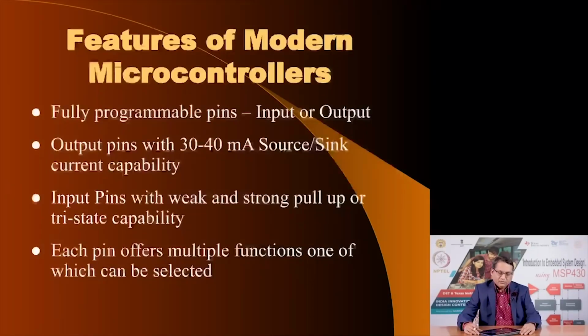The first important feature that modern microcontrollers offer are programmable pins. These pins can be programmed to either behave as input or output. Now, why is it important? When we are talking of a microcontroller, we are talking of a single integrated circuit. And a single integrated circuit, whether it is small or big, would have a fixed, limited number of pins. Let us say we have a 20-pin IC. Now, any 20-pin IC, or any electronic circuit for that matter, would require power supply pins, and so we would have to discount 2 pins for power supply. That would leave us with 18 pins.